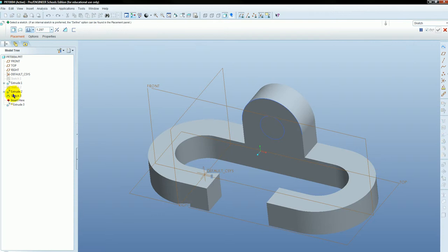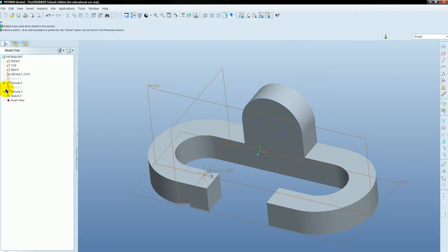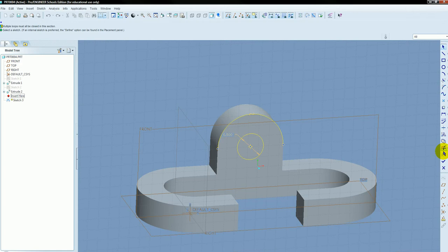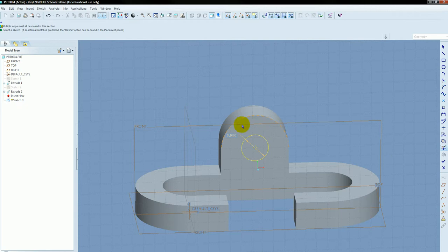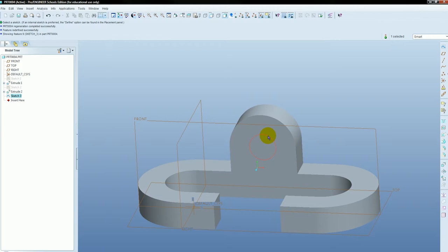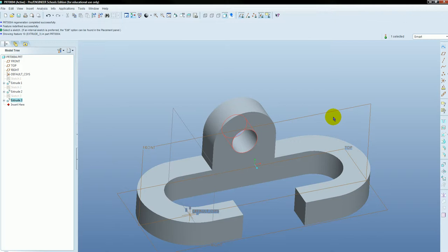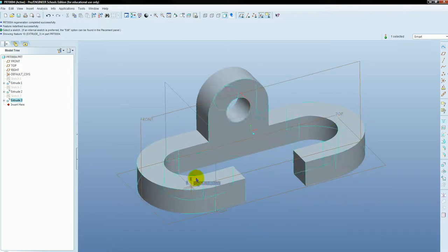See? So what I want to do is I want to go back into my sketch, sketch 3, edit that definition, and now I can just use the remove command to remove this. Since this was created from that center point, this is where it needs to be. So I can just finish this, then I can use the extrude. I want it to go through all, flip the other way, and remove the material. Once I have that, I've got this assignment completed. Again, this is exercise 3-35-2.